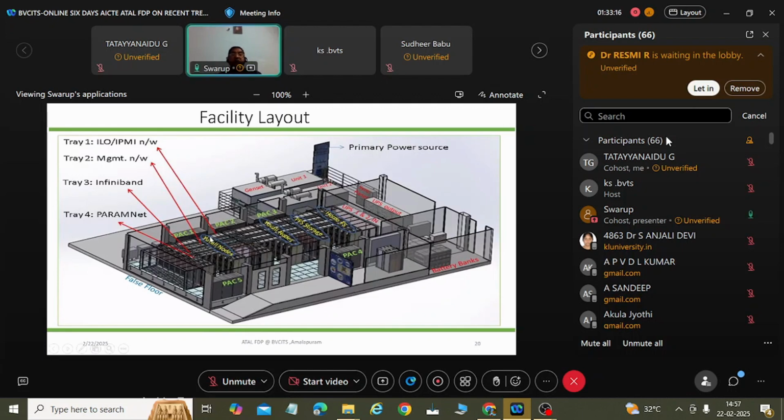So this is, like say, the primary interconnect, I have the InfiniBand, which is another interconnect, and I have management networking nodes, and this is another management network, IPMI, and then I have the storage nodes, and these are the precision ACs. This is the pack. So I have 5 packs. I need at any point of time only 4. This is the N plus 1. So it does a round robin to provide the redundancy. It is not that pack 5 is never used, it is a round robin. And this is the battery bank for the UPS.